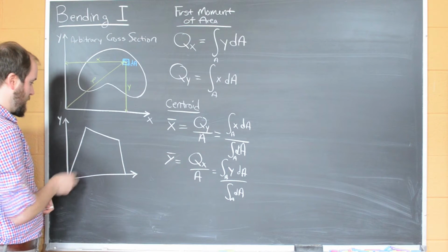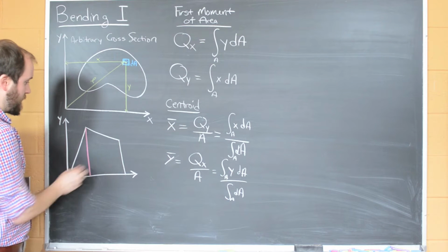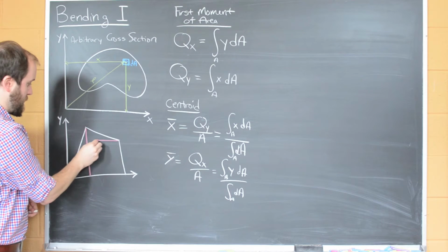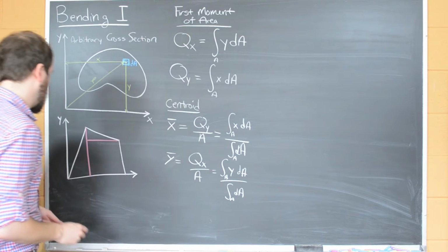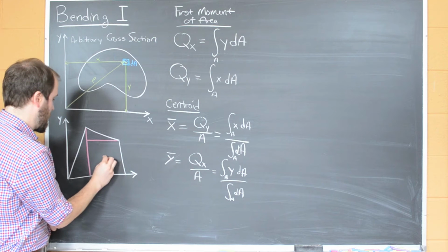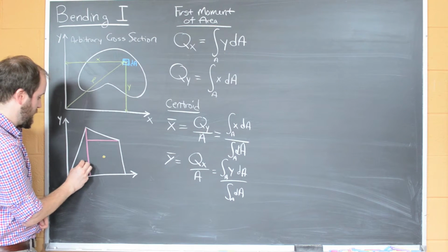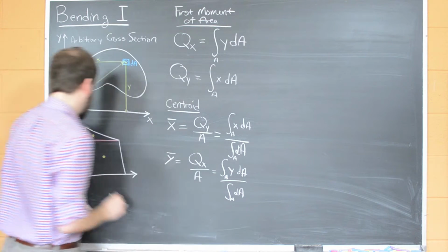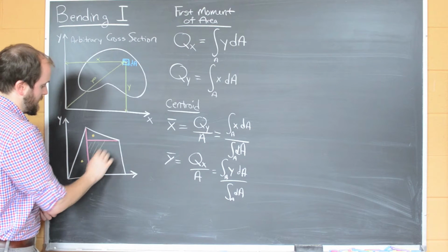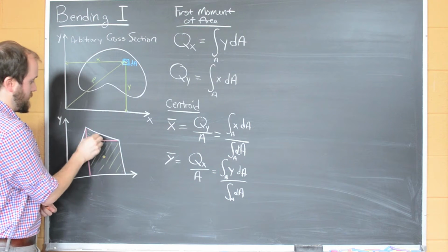And so what we see here is we can split this up into a triangle and a square. In this case, this square has a centroid that's going to just be half the height of it, and we can easily calculate the centroids of each of these two triangles, and we should usually be able to get the areas of these just from simple geometry.